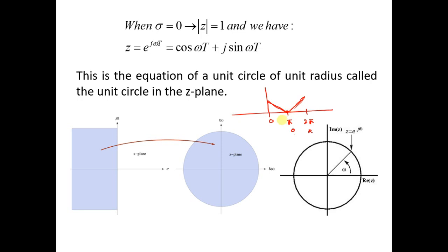If you do not take proper care, what will happen? The low frequency components will be interacting with the high frequency components, and your signal will become distorted. This distortion is called aliasing.